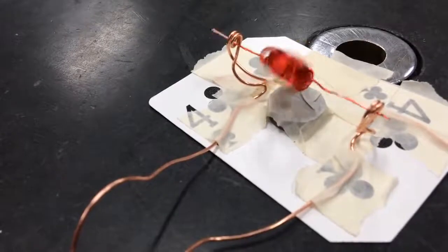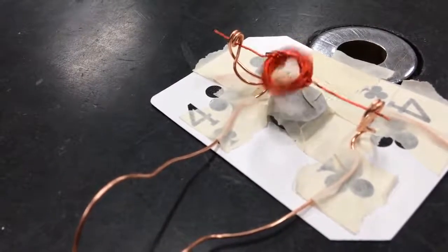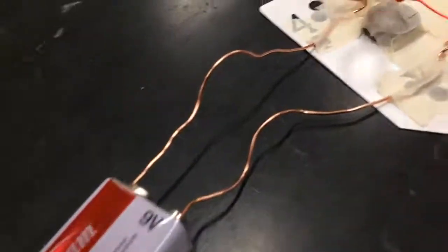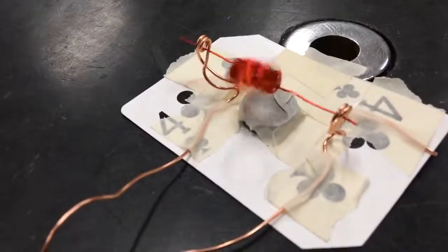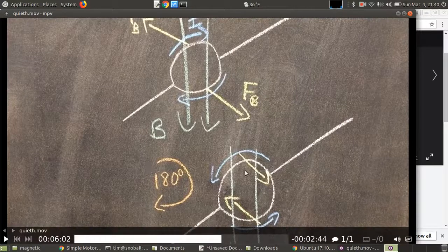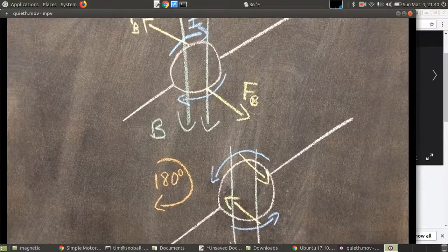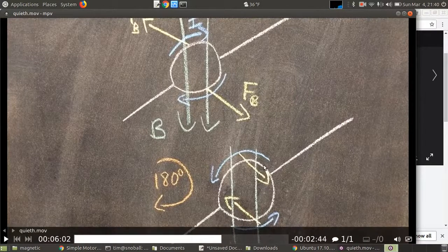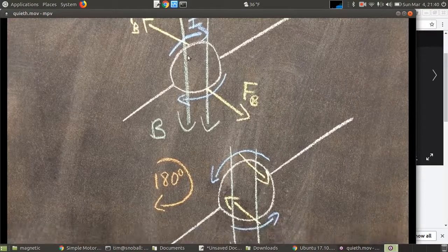And it's actually acting as a tiny little electric motor. The chemical energy of the battery is being converted into kinetic energy. So we can see it works if we just eliminate one of these two situations. If we just turn the motor off when it would be like this, and then it gets its push when the current is clockwise. It then switches off and coasts through the other half of its cycle and then gets a push every half cycle. It's not the most powerful way to build a motor.